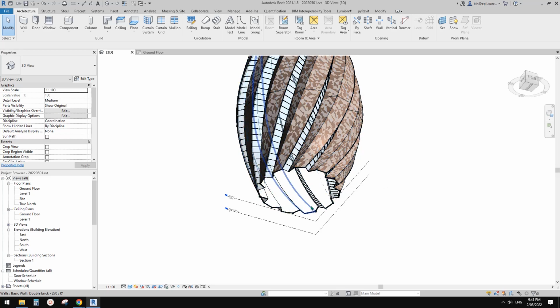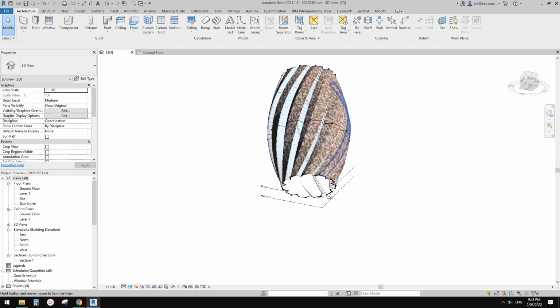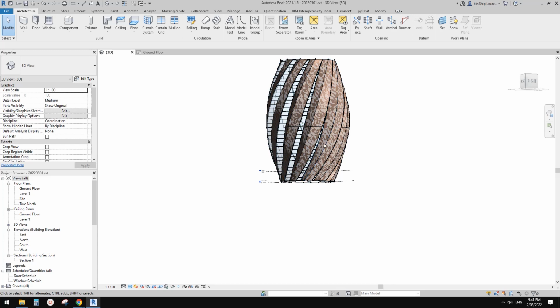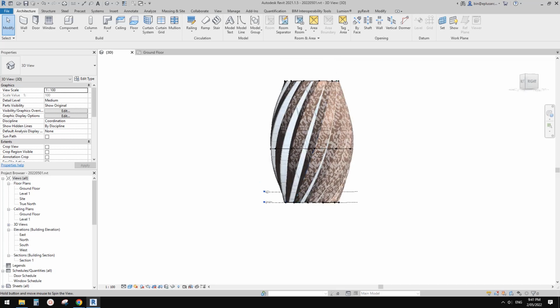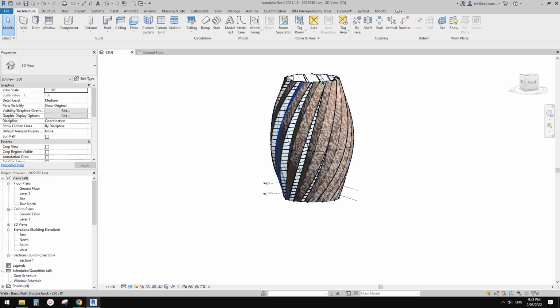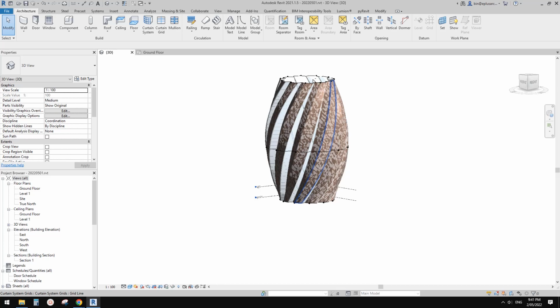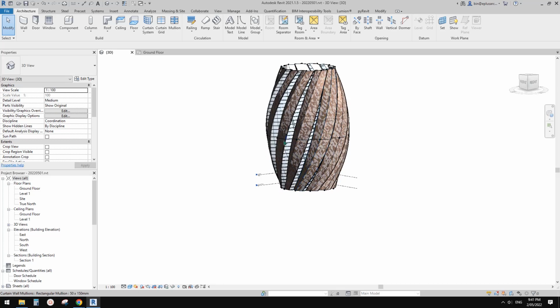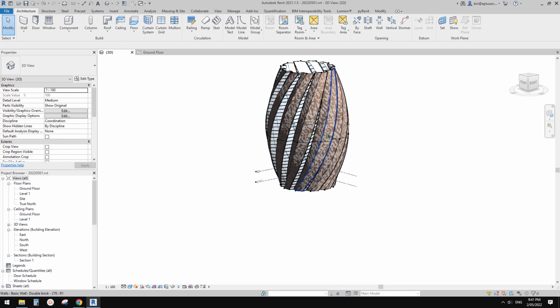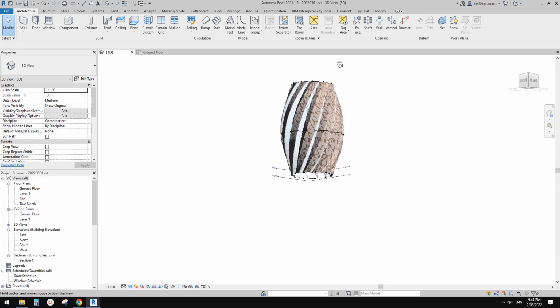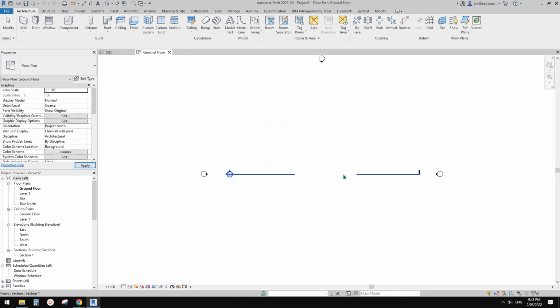create a circle and then use a divided path, and then we're going to place an adaptive family onto the path, and then use that as profile, and then at different levels, we are going to create another set of profiles on this level, and another set of profiles on this level, and all these levels, the height, the size of this profile can be adjusted.